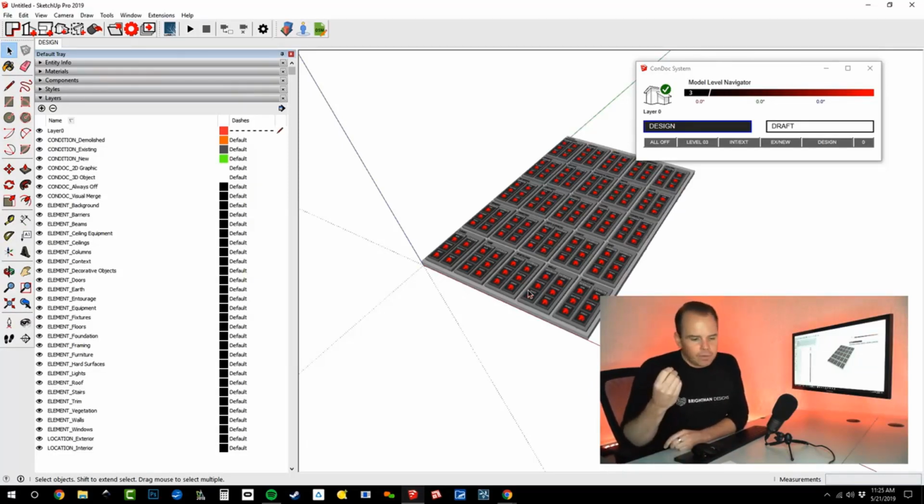Now, here's the thing. There's kind of two different ways to use these model organization guides. You can either double click in and find where you want to model, and so get into the right nested group of the model organization guide, and then build your model in each place where it's supposed to be. Or you can just build things and cut and paste in place. All right. So I think the easiest thing to understand is modeling things where they're supposed to be. So we're going to do that first. And then after that, I'm going to show you the way that I usually work, which is I just start modeling things and then I cut it and I paste it where it's supposed to be. So let's get to that.